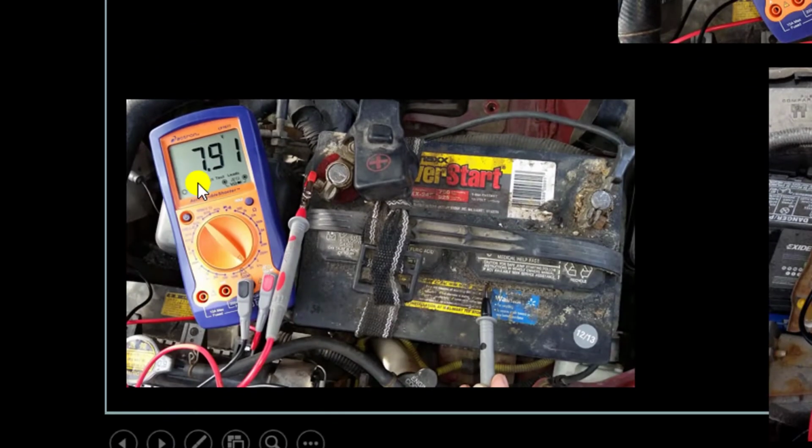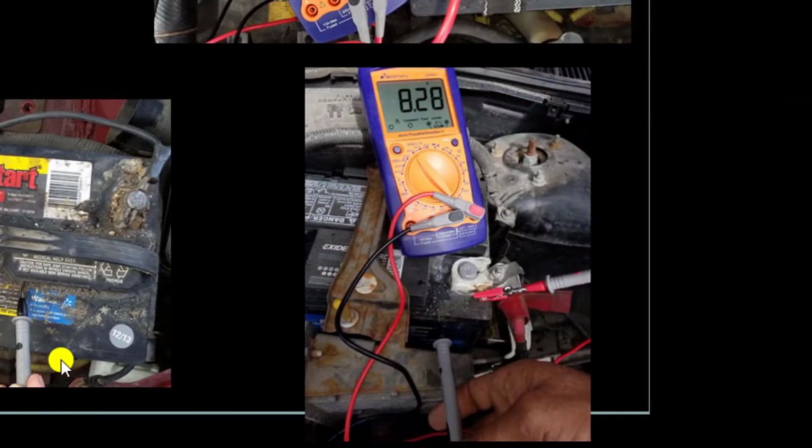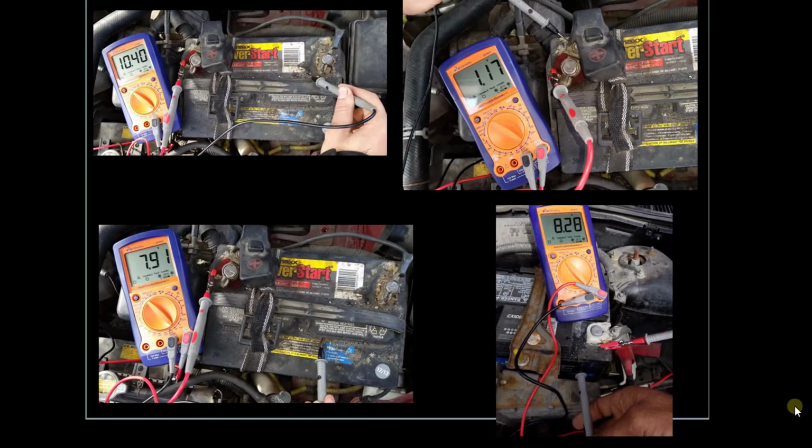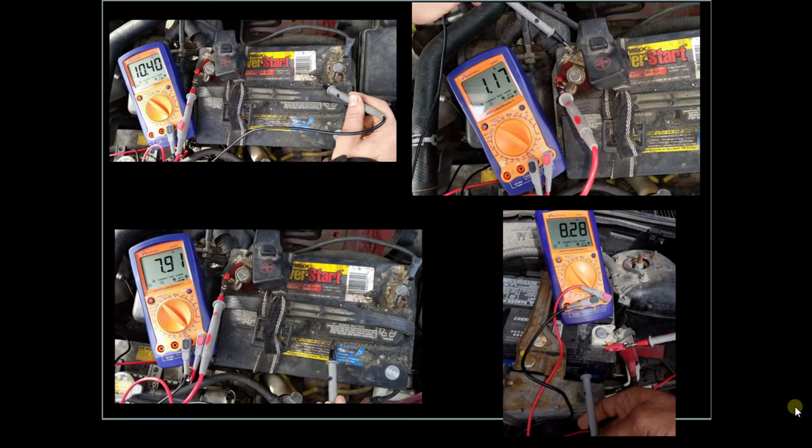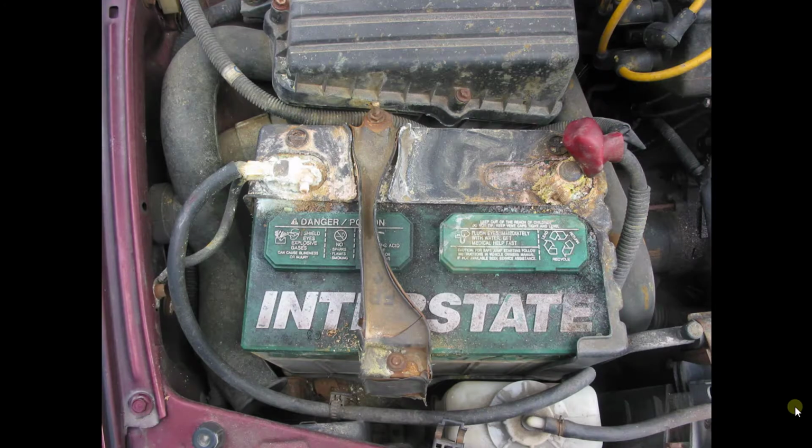There is the positive terminal attached here, and there's your dirt right around the vent cap, causing a 7.91 volt drop. This is the most dramatic one of all, where right where I am here is considered an extension of the negative terminal, and I'm able to provide 8.28 volts. So essentially, if I see voltage like this, that means that this battery is slowly discharging through the dirt on top of the case. So here's our dirty battery, here's a clean battery.